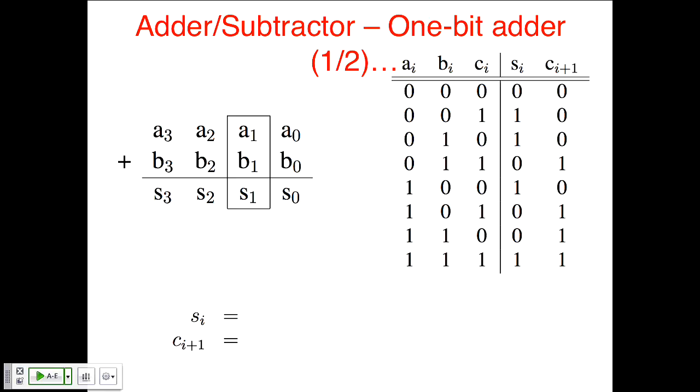So just to pull out a few of these, so if everything's 0, the sum will be 0 and the carry out will be 0. If A and B is 0 but there's a carry in, the sum will be 1 and the output will be 0. So notice you're adding 3 1-bit values. So the sum plus carry, informally the value is going to be somewhere between 0, 1, 2, or 3, depending on how many 1s you have in any row of this table, right? So there's 1, 1 here, there's 1, 1 here, there are 2 1s here, so it's 0 plus the carry out. There's 1, 1 here, 2 1s, 2 1s, and finally this last row, all 3 are 1. So 1 plus 1 plus 1 is 3, right? So sum 1, carry out a 1, okay? So that's 3 in binary, right? The carry out of that bit position goes to the next bit position.